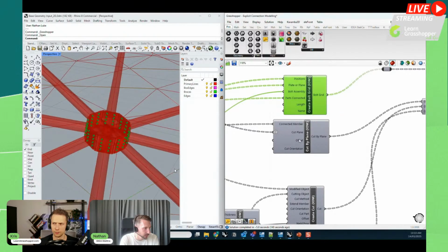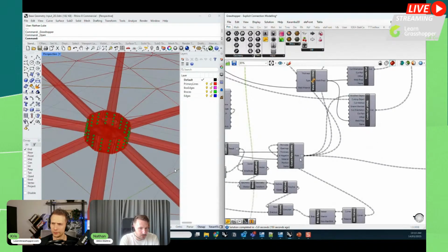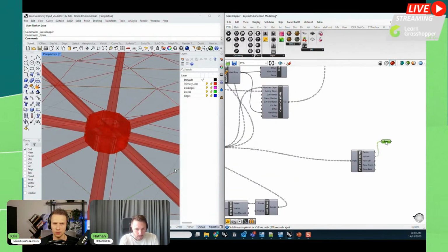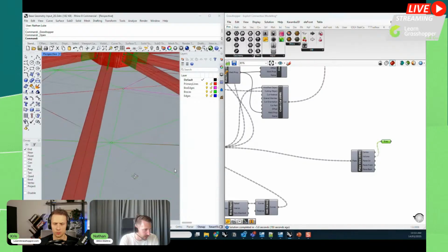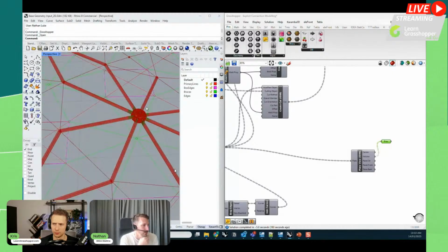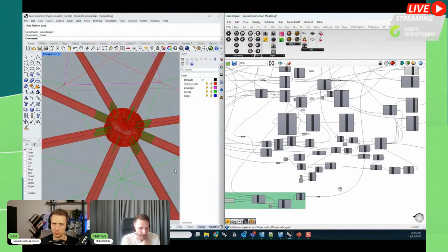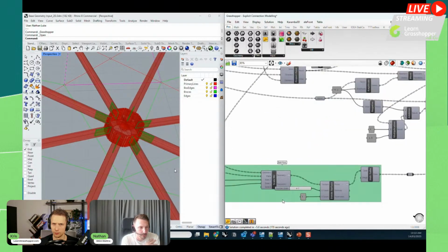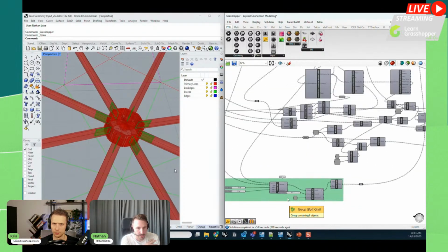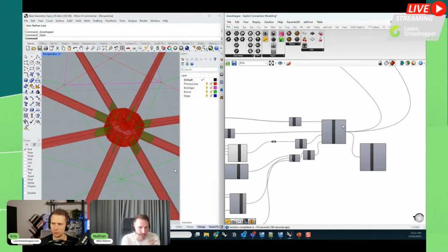If I turn the preview on here, you can see how the bolts are defined, and I'm using logic to create all the cuts, all the plate geometry, these stiffening plates in these members, etc., using Grasshopper and defining the geometry based on cross section sizes, etc. So with a workflow like this, I can take any data that I have in the model, such as cross section sizes, dimensions, and use those to drive my connection design.